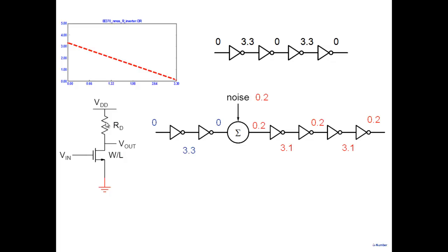So when you switch something, there is a current that flows into the ground. The current flows into the ground, which is here. So the ground is carrying various kinds of transient currents. And if it has a resistance associated with it, then there is a voltage drop in the ground also. So there are possibilities of this getting corrupted. There's not a pure 0 volt. This may be higher, lower, and maybe randomly varying depending on what all is connected to the ground. Similarly, my VDD can get corrupted. VDD may also have various kinds of ripples and noise.